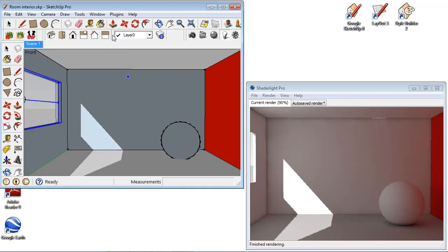There's a quick question here, Martin, about animations and how GI is calculated when you're rendering an animation. When you're rendering an animation, basically the GI is calculated in each scene. The GI is accurate enough that from frame to frame, you really shouldn't notice a flickering effect, which can be visible if the GI isn't up to it. So you should be okay with that, and particularly in 2.1 with the new features, that has helped a lot as well. But GI and animation work absolutely fine. So that's not a problem.